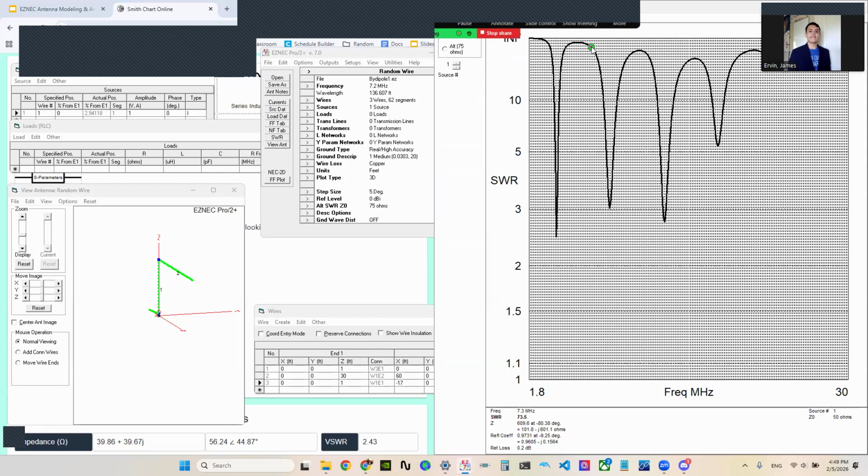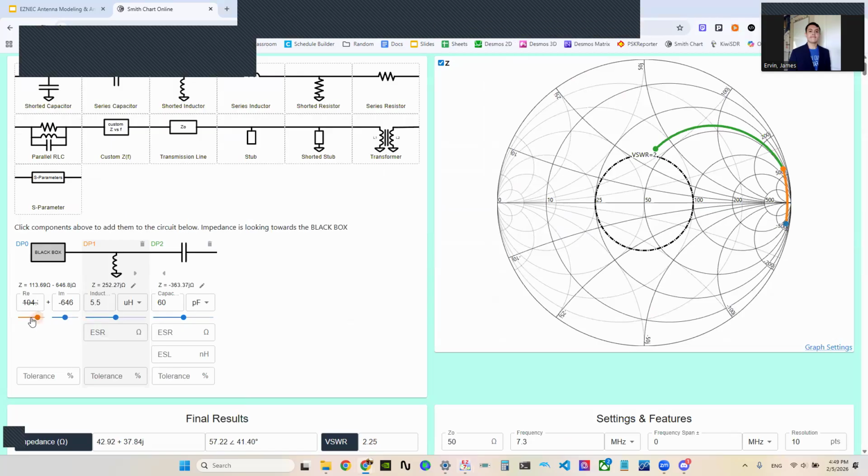We're going to get our new measurement of impedance. We have an impedance of 101.8 ohms minus 601.1 ohms. So, okay, cool. It looks like we're just going to need to adjust the inductance a little bit. So let's do 5. Yep. So just decreasing our inductance by 0.5 microhenries. We already just re-resonated the system.